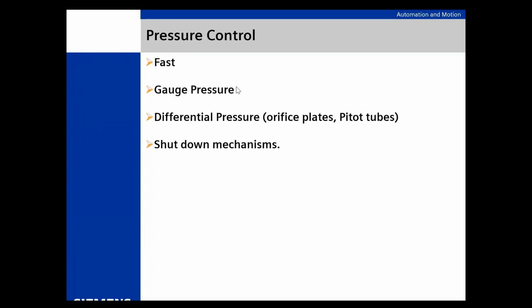The other thing is, you look, it says, how about differential pressure, orifice plates or pitot tubes? Yeah. Are they accurate? Not hideously. I mean, they're not the most accurate thing in the world. They work. In certain applications, that's what you use. But again, if you're giving me a 5% measurement, I can't give you a tenth of a percent control resolution. Not happening. Just can't do it. And this is stuff that needs to be thought about when you're tuning that loop. How good can this be?